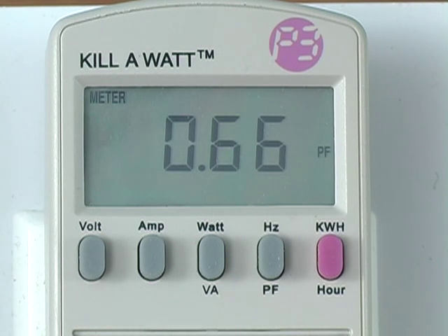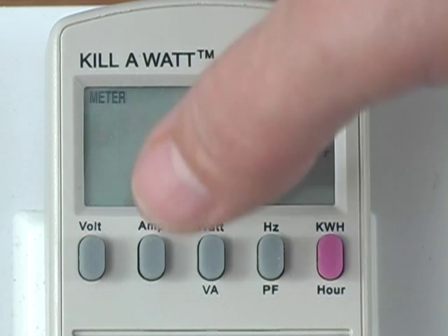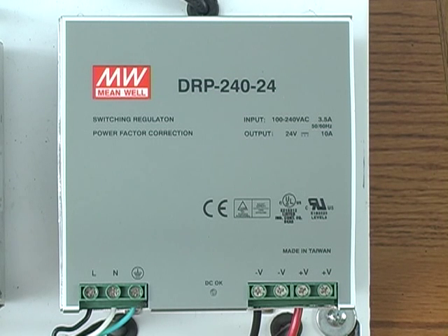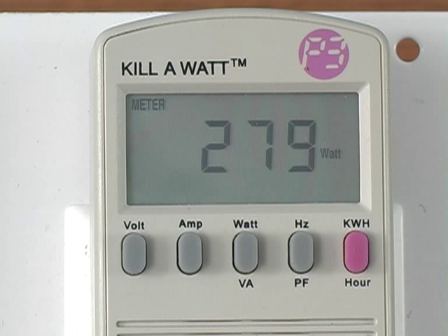The datasheet for this supply has the efficiency listed at 88%. It is understandable why this unit has a higher input current, as the power factor and the efficiency are lower than the PULS unit.